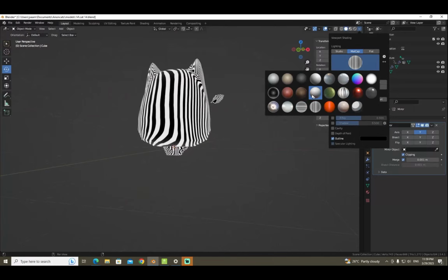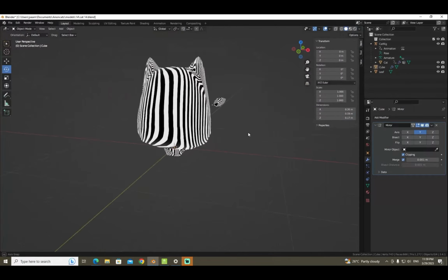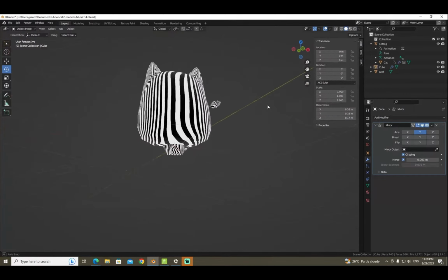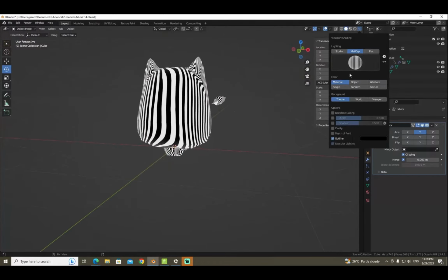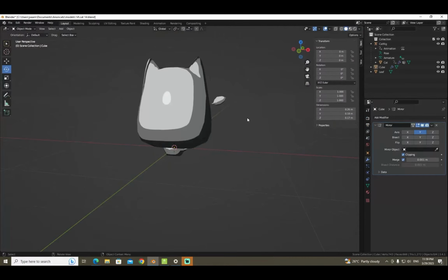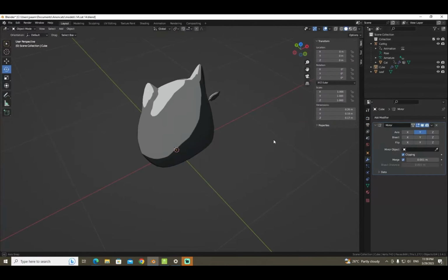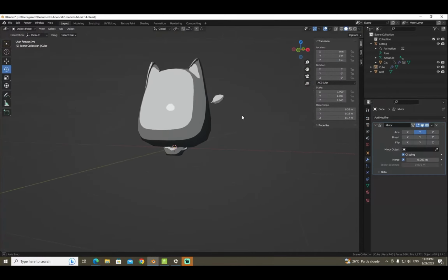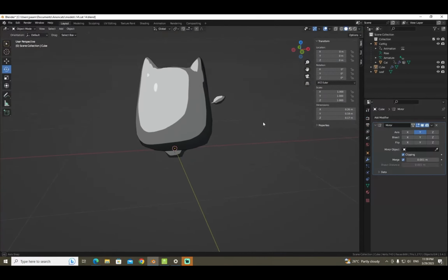Right, so I guess one tip for 3D modeling is that matcap is really useful for checking your normals. If your normals are kind of messed up, you would very easily see it with matcaps. So it's always a good idea to cycle between various matcaps to see whether you've messed up your normals and stuff.